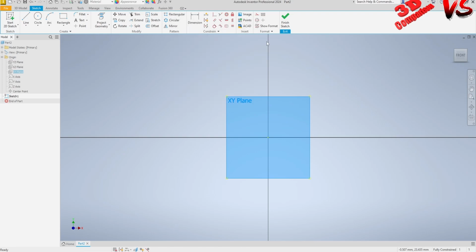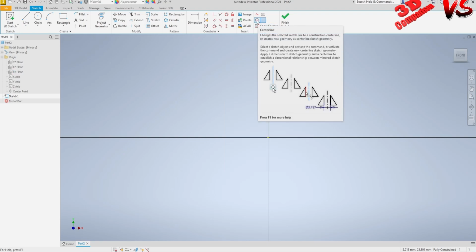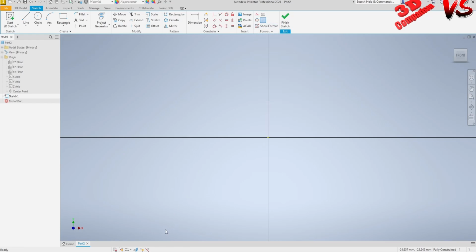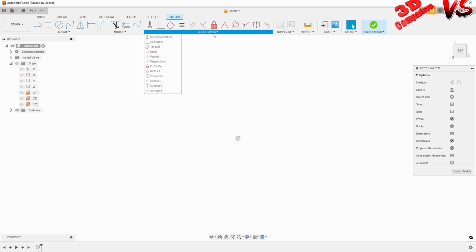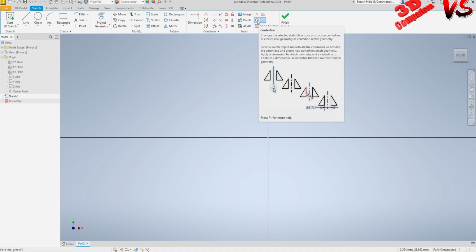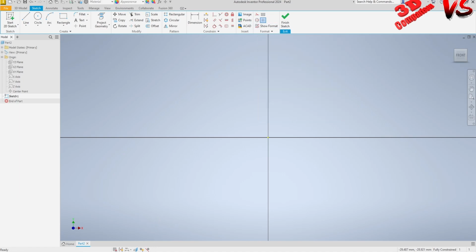And if you want to convert rapid elements, we can do that over here, for example, for center line. Or if we want to make something for construction, we can use those features over here. Within Fusion, we're going to have the constraint position over here. And for those construction types, we can rapidly add them over here. So we see the center line and the construction with those two icons. They will be, in this case for the center line, quite similar to those within Inventor.